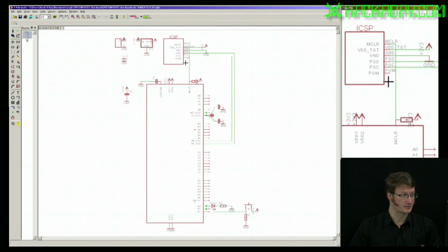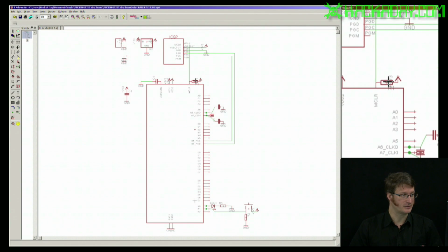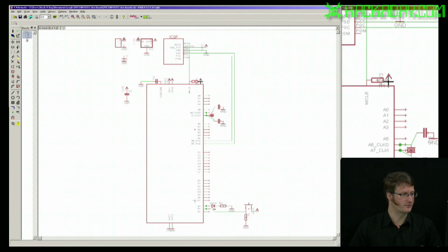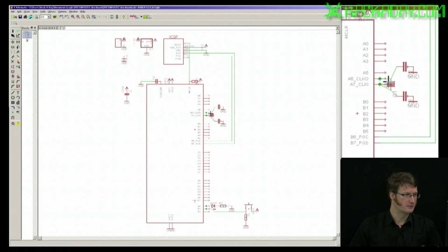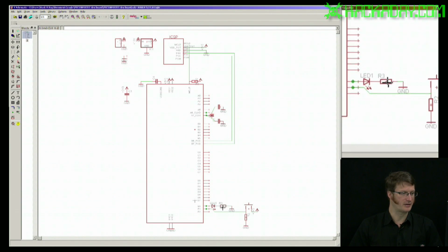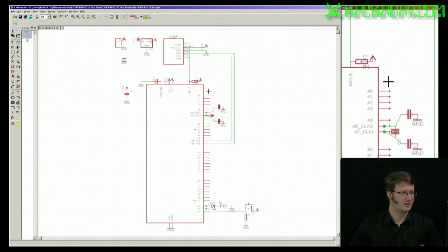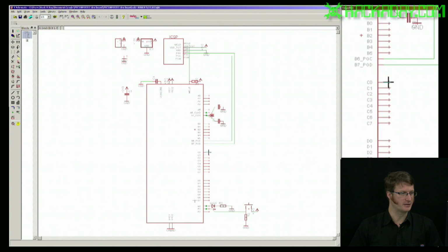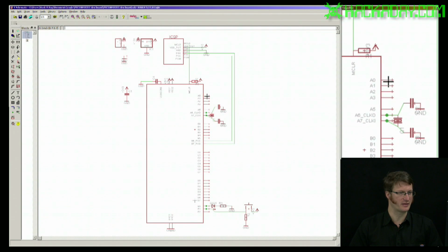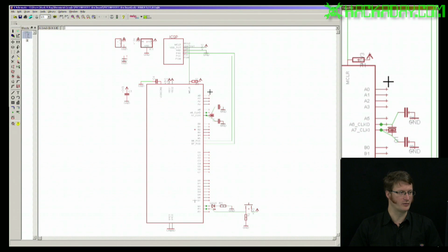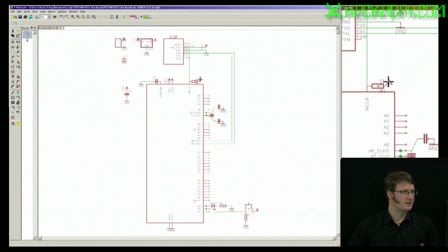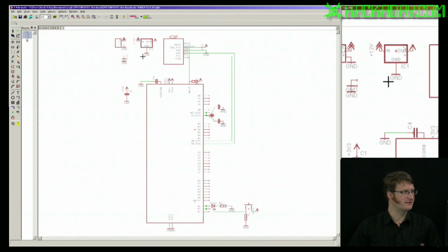in-circuit serial programming with a resistor pulling memory clear high. You need that in order for the processor to run. We've got our crystal and its 2 associated capacitors, our LED, and a button. And then every I/O pin has a header pin coming off of it so that you can connect to whatever you want to on the prototype board. So that's our schematic as it sits now.